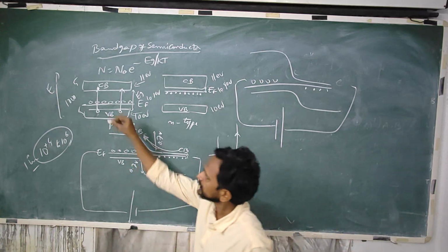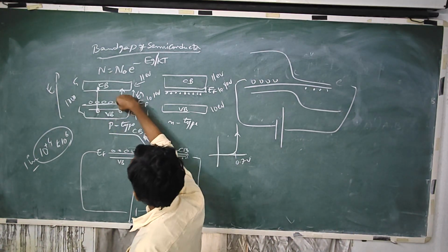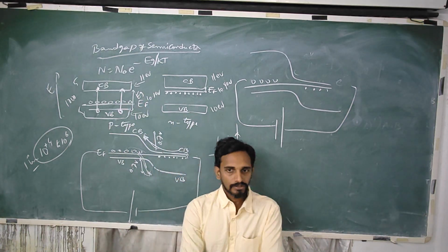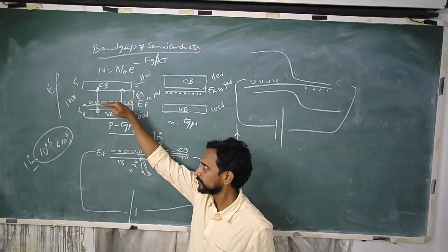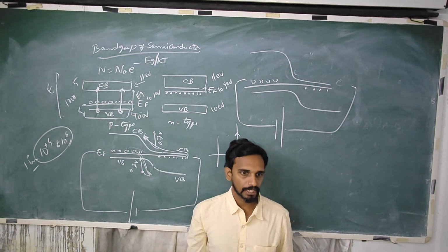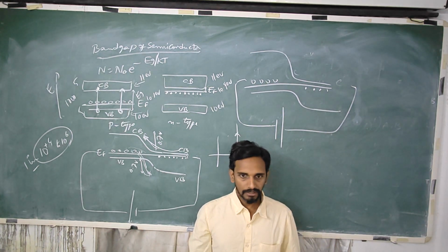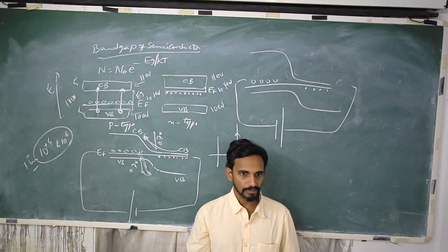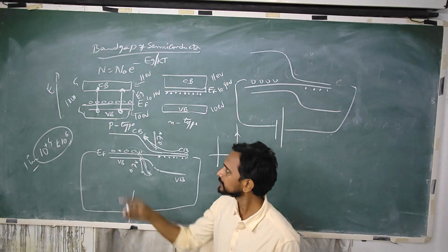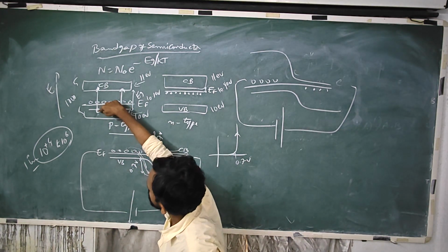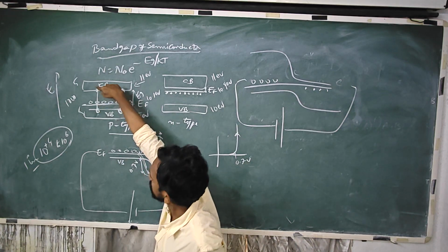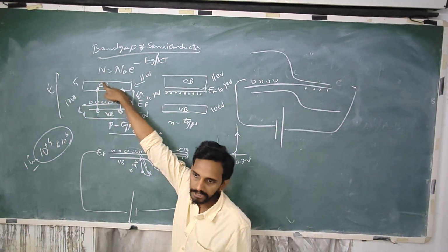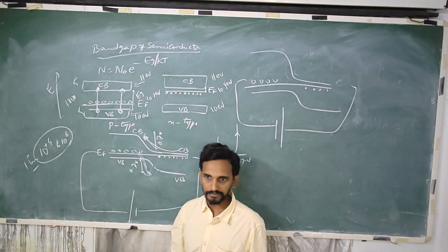And now the carriers are coming from the base silicon atoms. They exist both on p side and n side. The carriers are coming by thermal energy. So when you supply sufficient amount of temperature, heat, they take that heat energy and bonds will be broken in silicon atom, and you get electron hole pairs.